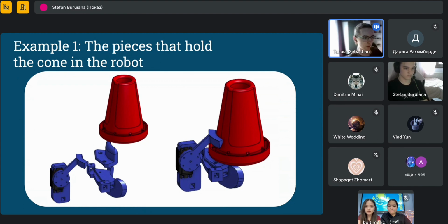As you can see, the pixel will land on this part with an edge that holds it, and there's the claw that presses it against the edge. So it was really important last season to iterate that part because we found out early when we printed our first prototype. It wasn't like this. It was a really big 3D print, and it was kind of messy. We had problems with it and ended up printing it a few times, so we decided to just make it out of 2 parts and be able to change it very easily. After I did this, I think it took us 1 day of 3D printing a few prototypes to get it perfect and to make it work perfectly.